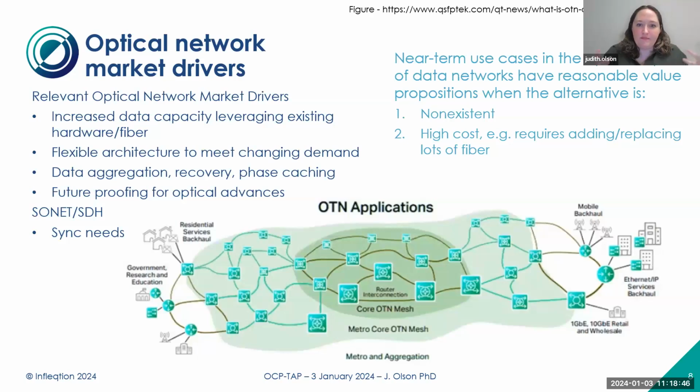So, you already have thousands and thousands of miles of fiber out there. It tends to be single mode fiber, which doesn't have great dispersion properties, doesn't have a large transparent region, but it's already there. So if we can find a way to leverage the existing hardware, the existing amplifiers, and all the optical components that are in there, it makes it a lot easier to transition over. And it looks like there is a high level of compatibility there. I'm still digging into details, but I have not found anything that makes me think it isn't possible at this point.